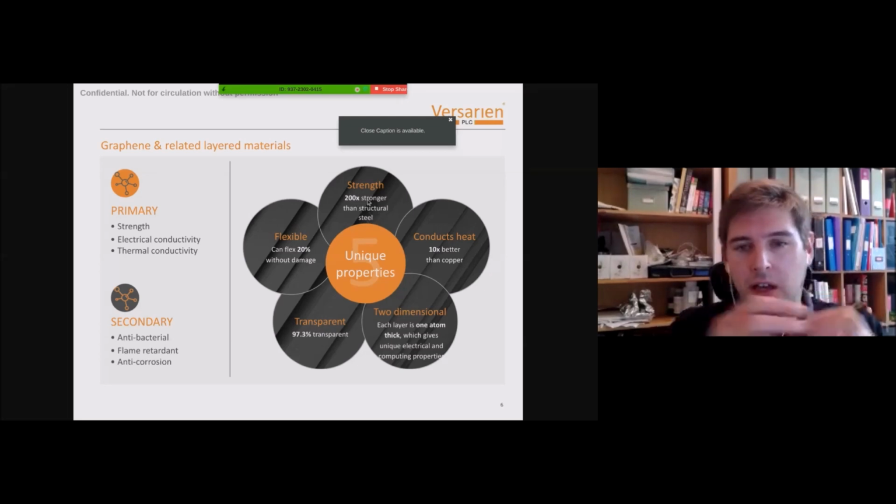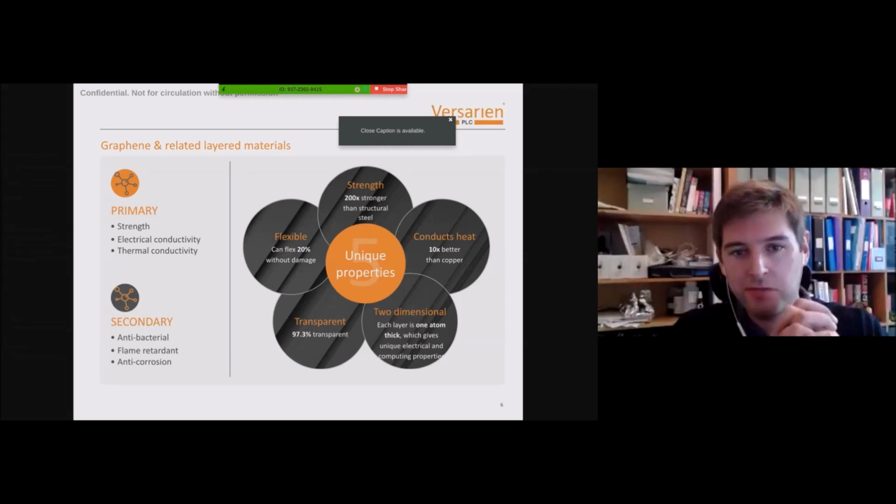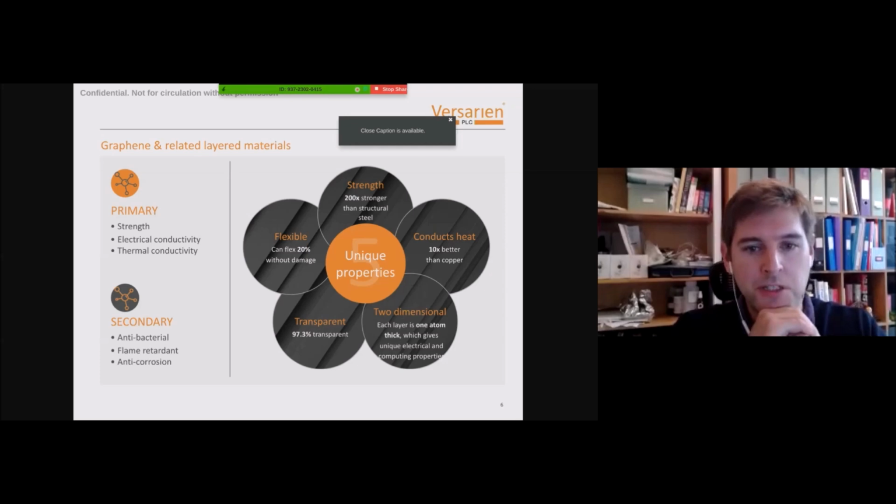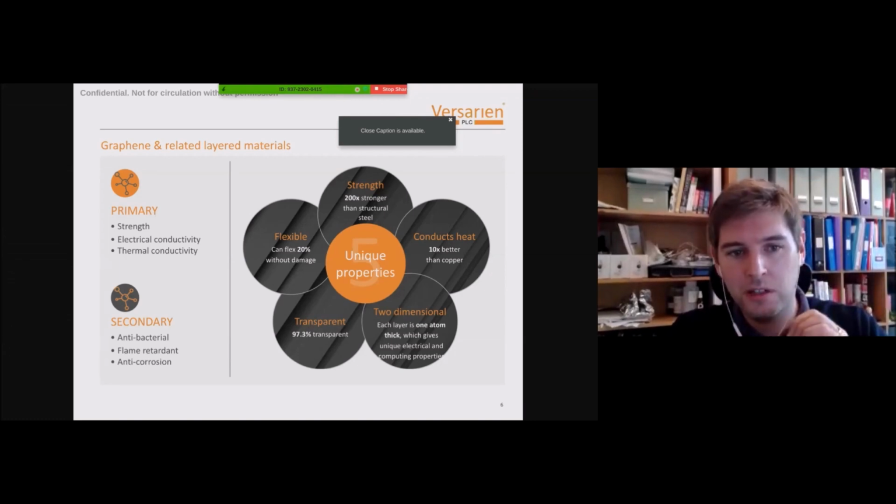So when you get down to these single atomic units, graphene becomes incredibly strong. It's also very thin and very flexible, so it can tolerate a lot of damage. And in terms of the color, when you get down to that single thickness, you get something very transparent. Each layer of graphene is absorbing about 2% of light. But as you increase the number of layers and go towards a more graphitic structure, that's why you start to see this opaque structure.